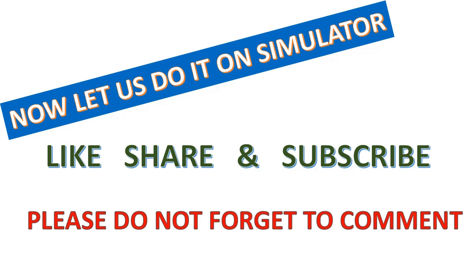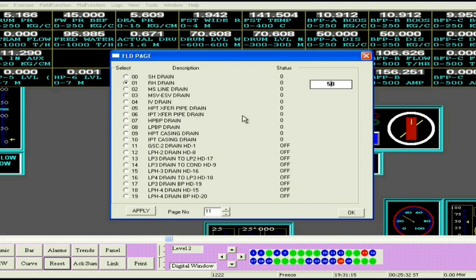So now we are on the simulator. We have loaded the file and here we are opening the drains. That is the first thing that we are doing. First of all we open the drains, the superheater drains, the reheater drains. Superheater drains we throttle to 5%. The reheater drains also we throttle to 5%. And then the main steam line drains we throttle to 10%.